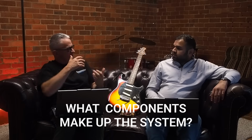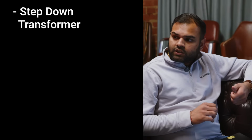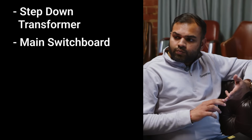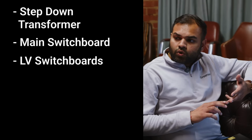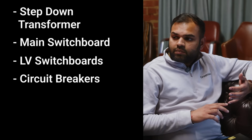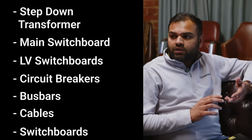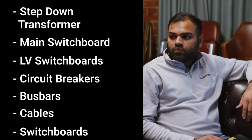So we've got this LV system. What are the components that actually make up the system? Transformers and stuff? Yeah, so particularly an LV system would include step-down transformers, main switchboards, LV switchboards if there are any between the main switchboard and transformer, then circuit breakers, bus bars, cables, or switchboards other than main switchboards downstream.